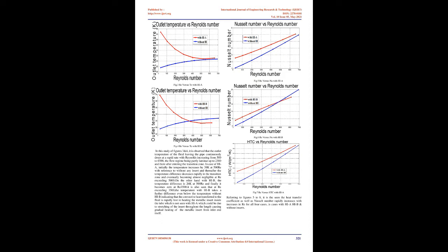Their results indicated increased heat transfer with decreasing tube ratios and increase of Reynolds number. MMK Bhuiya 10 studied double helical inserts under turbulent flow condition at double helix angle of 9 degrees and highest Reynolds number 51,000, where that condition achieved 215% increase in thermal performance.